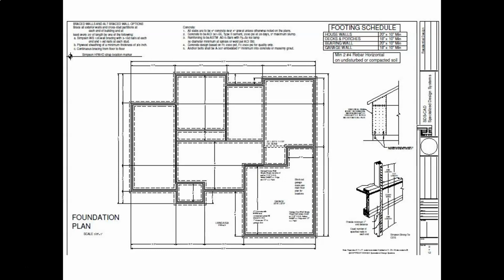So it doesn't have all that illustrative kind of information that I was just going through. But anyway, we have our dimension strings. This looks like it's nicely dimensioned, actually. At every jog, we would have a dimension cut. So yes, that all makes sense. And then we have an overall that matches it exactly, and the same here. Jogs, dimensions for every jog. I'm not sure what this is, going here to the center line, and I can't read this, but no matter.